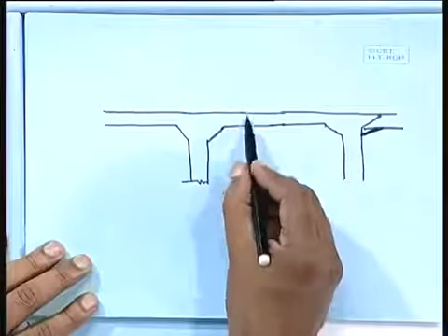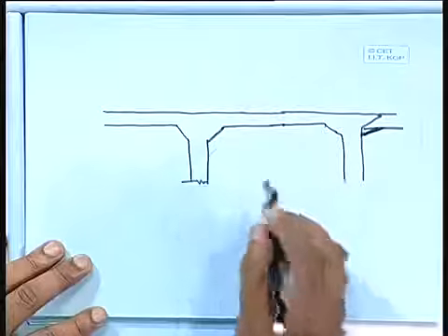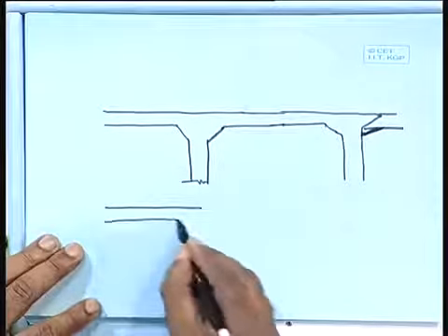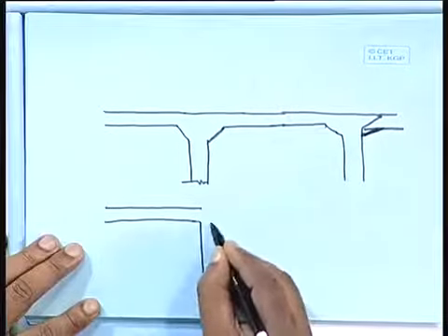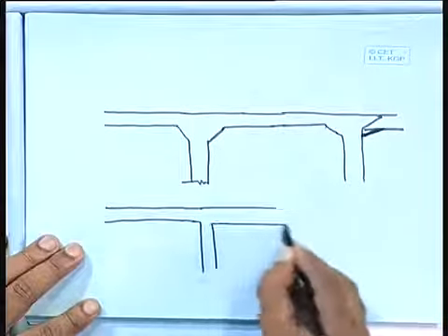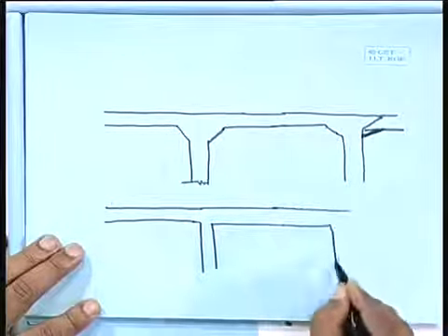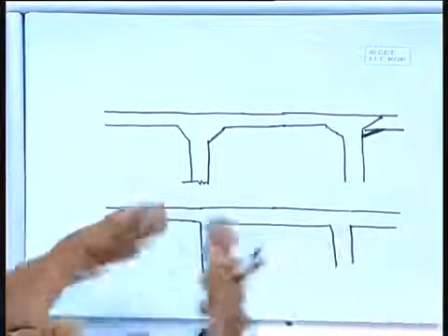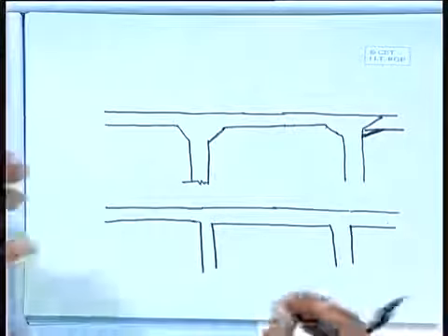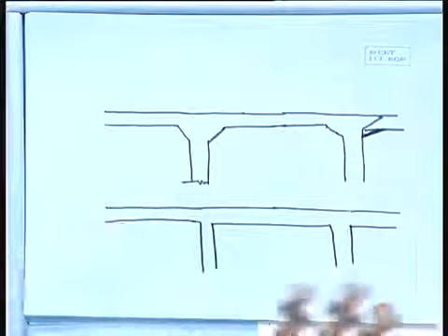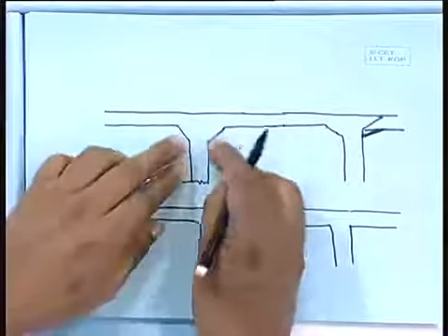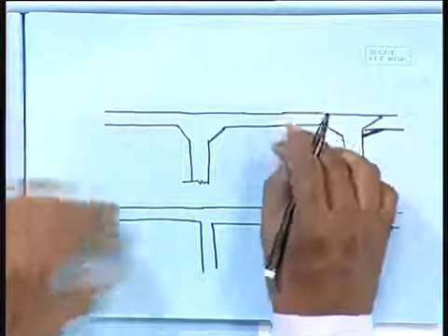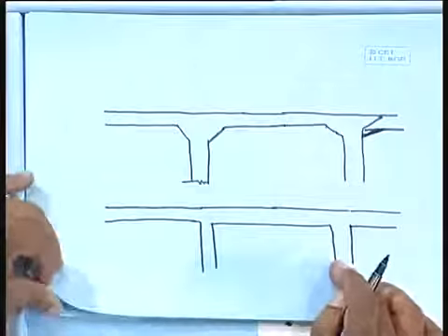So, this is your flat slab. We can also take it simply as a flat plate, as if it is supported by columns only. There is no beam. It is just supported over different props, or supports, and over that you are keeping one plate. Whereas here you are making the support a little bit bigger, and then over that you keep the slab or plate. So, this is your flat slab, and this one is the flat plate.